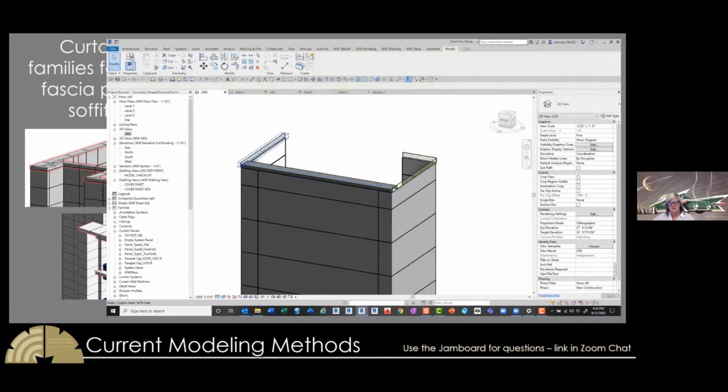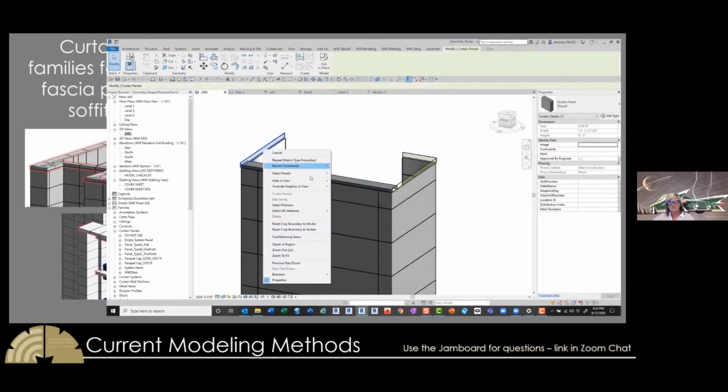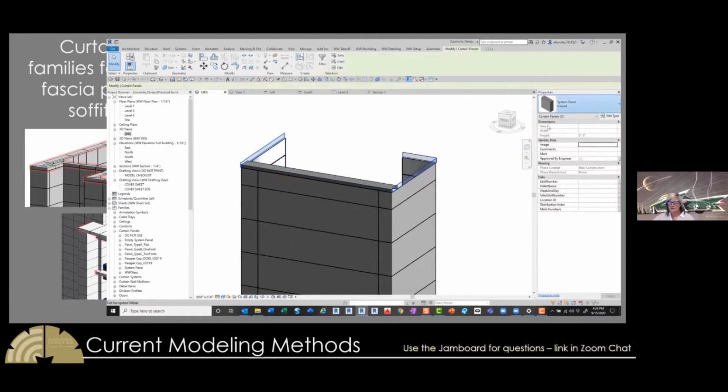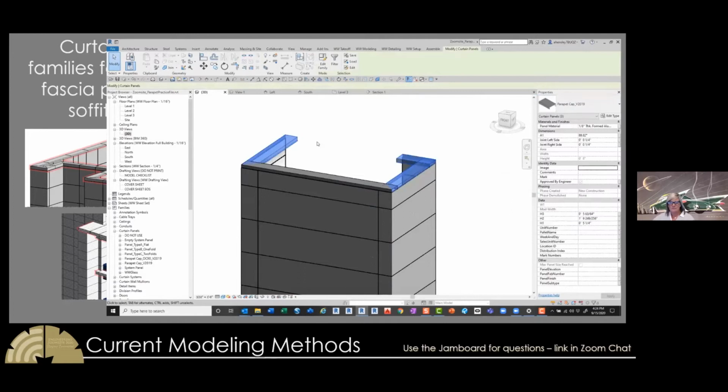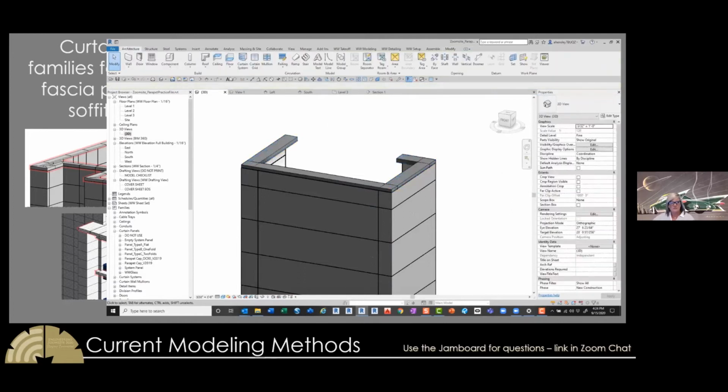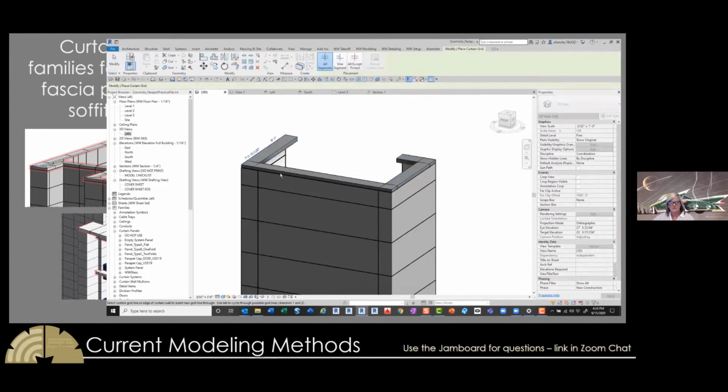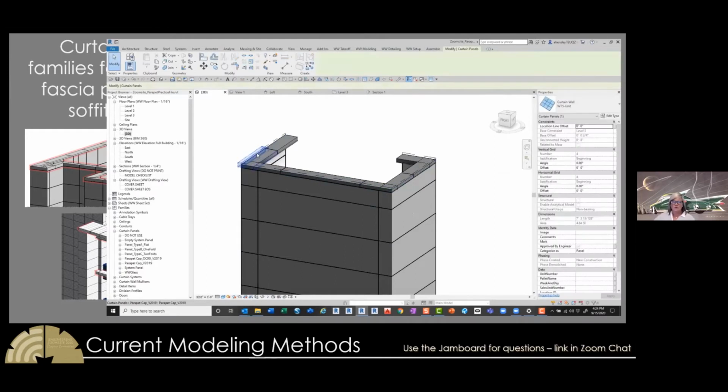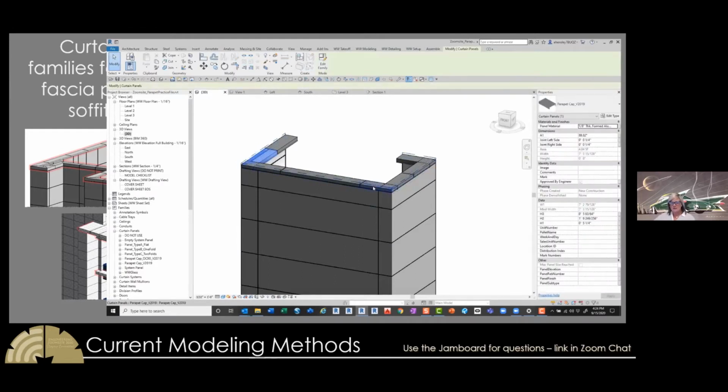And then I'll switch out the rest of those panels. Just going to select all, switch it out. Now I'll add some joints by just adding some curtain grids. Again, I'm not being specific about where they go. And right now we have left and right outside corner families, but this is an area we're definitely going to improve on.